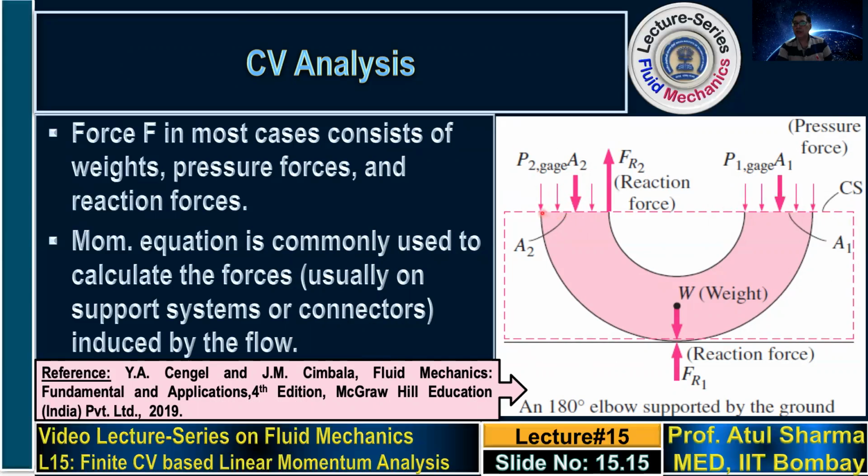Note that here the pressure is involved as a force, the weight is involved as a force, and then you have a reaction force. As I mentioned earlier, other than the reaction force, most of the time we want to generate a control volume such that at the control surface we only need to bother about pressure forces, and other than pressure forces we are bothered about the weights. So we should not take control volumes where we have viscous forces.